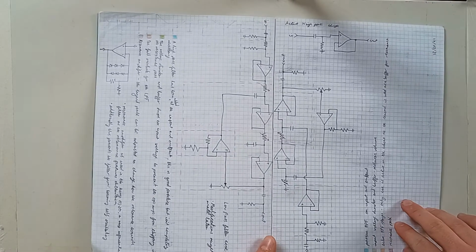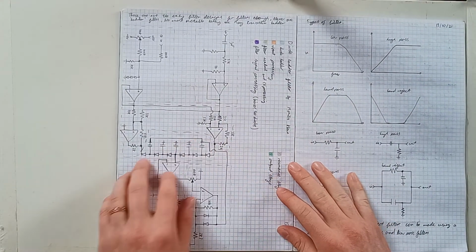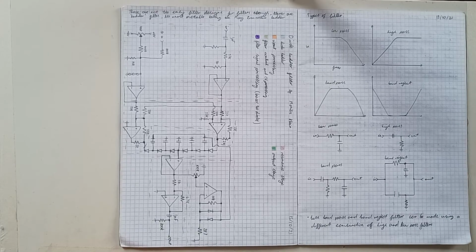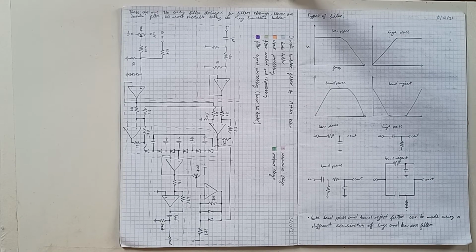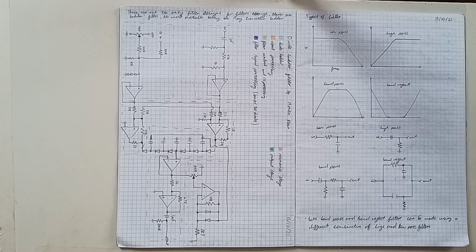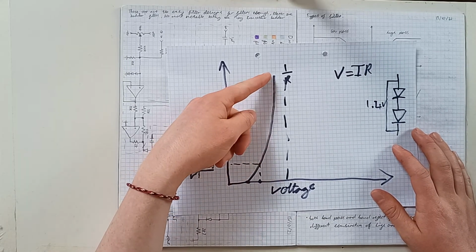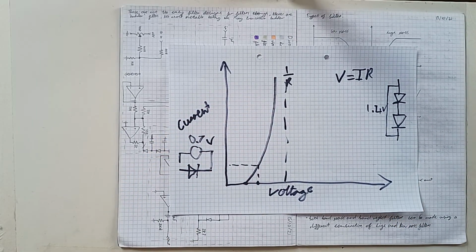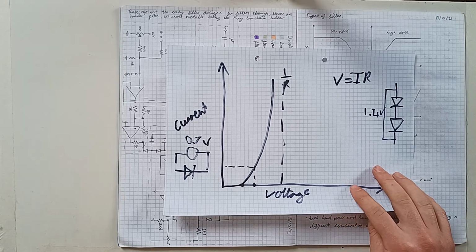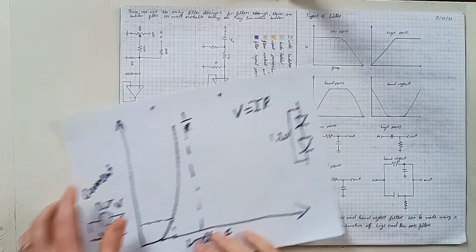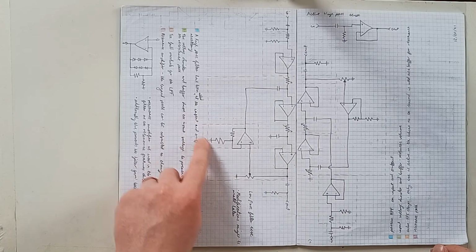Whereas ladder filters, specifically the Moog transistor filter, is very well known for how smooth it sounds. And that's, again, down to how the resistance in a diode changes, because it's this nice exponential curve. So by increasing the voltage by a little amount, you get, or exponential and logarithmic, they're kind of interchangeable, but it's a logarithmic curve, whereas this would be slightly more linear.